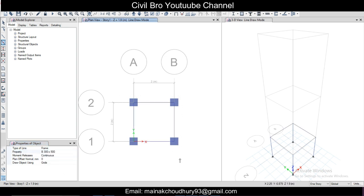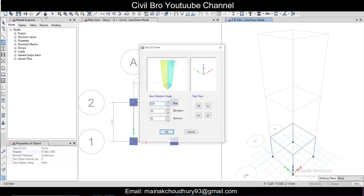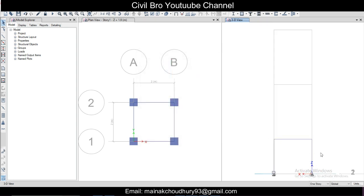Just draw the beam here, and we'll just set this 3D drawing and click on display, and simply go to view and set 3D view, and we'll do this 90 for selection only, 0 and 0. Okay, so just click on escape and we'll select the beams and columns, and then we'll do here